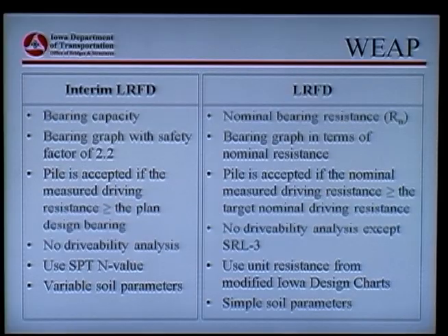So in the interim LRFD design procedure, you do not need to perform the drivability analysis. Whereas in the LRFD design procedure, if you run the WEAP that I'm going to show you, you could perform the drivability analysis if you want to, but it's not required except if you have a structure resistance level at 3. Okay?